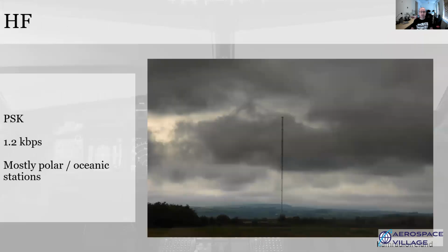There are also options to transmit ACARS over long wave, high frequency transmitters, and this is reserved for oceanic and polar regions. There are actually only 15 transmitter sites and speeds are incredibly slow, and this probably also explains the very high costs of using these services.